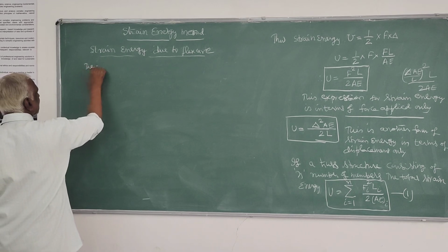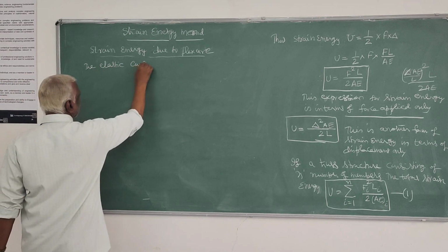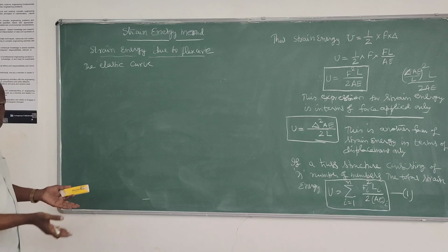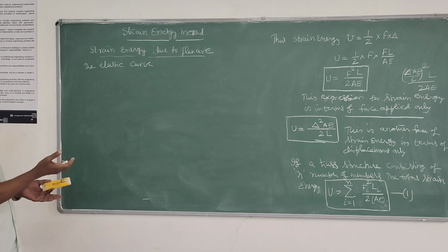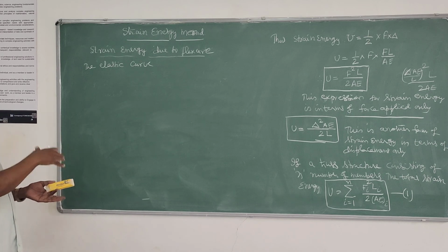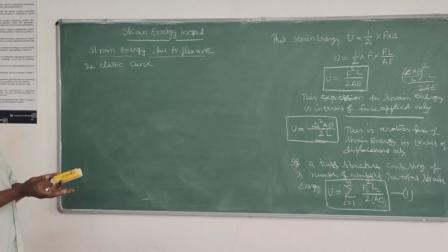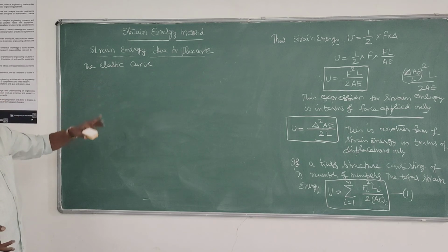Due to flexure, the particular member undergoes bending deformation. It bends with compression in the top fiber and tension in the bottom fiber. That is the actual deformation shape, and that shape we call the elastic curve.